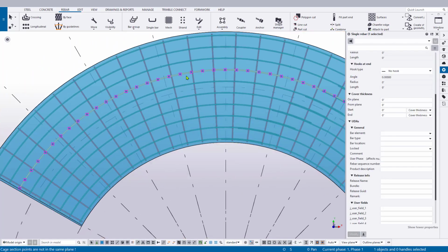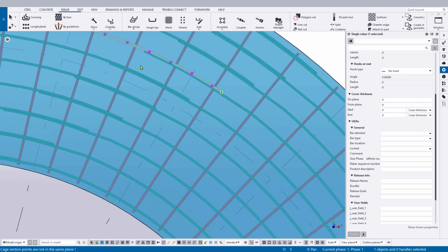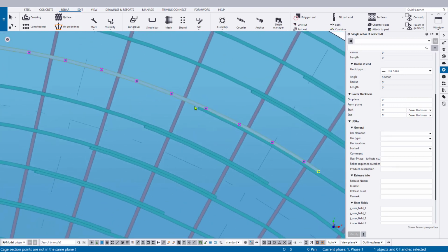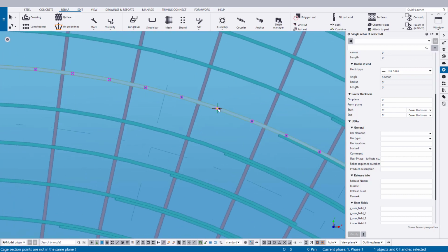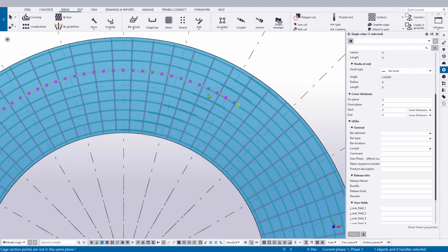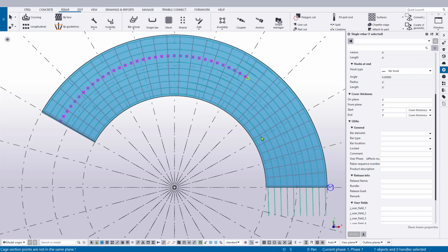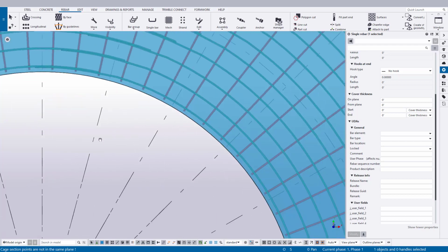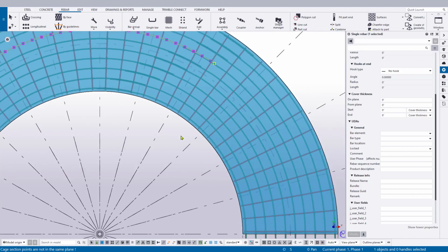The reality of it is there's no copy offset, right? So, this splicing and this placement, these are all different click points to create the curved shape of the bar. So as a user, if you were to model this completely manually, I would create construction circles at every space that a bar would exist, both where the bar is and then an offset for where the splice bar would be.